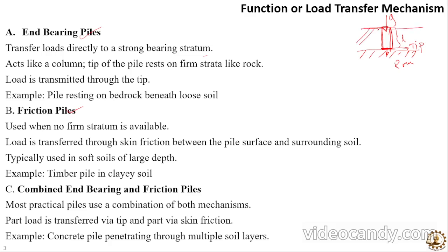Suppose in this zone the soil is too loose or the bearing capacity of the soil is less. In that case we can use the end bearing pile and transfer the load directly to the hard stratum.